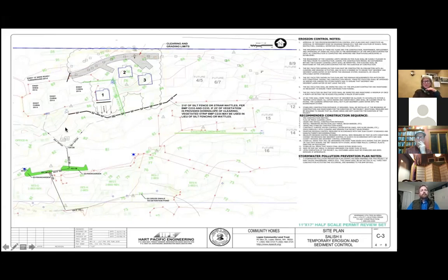You keep this as grassy, and you're disturbing all of this, right? You can see this is the area that's going to be disturbed because it's looking like this. And you keep this grassy area right here and just allow all of this water to be dispersed and then sheet flow over this. And then we've got a couple of rain gardens here.